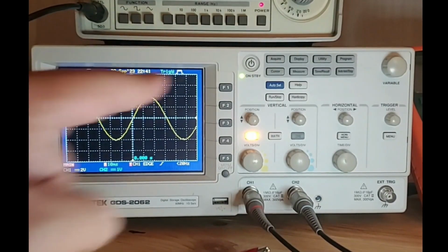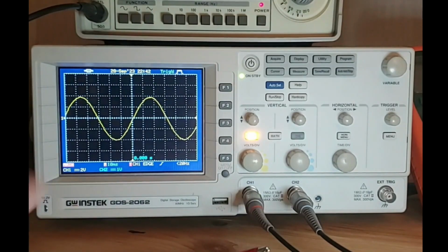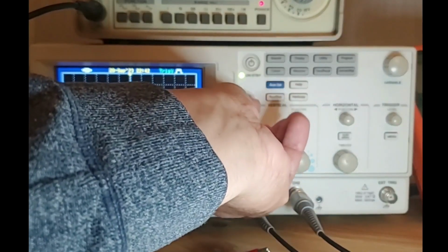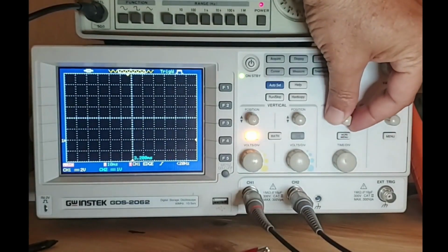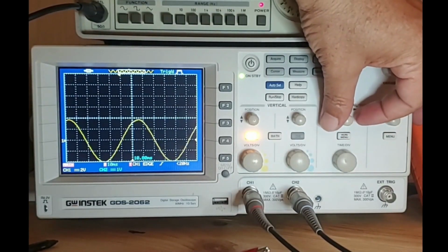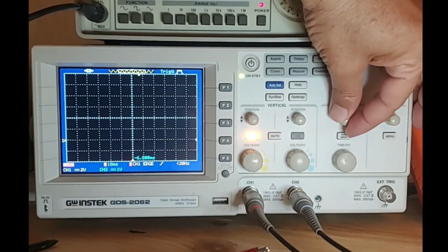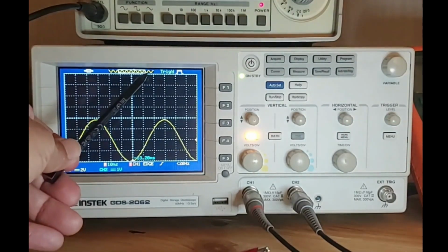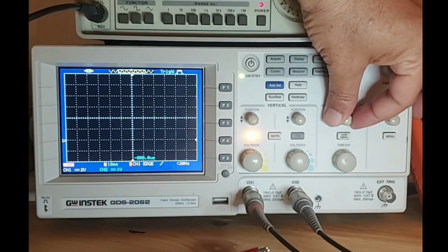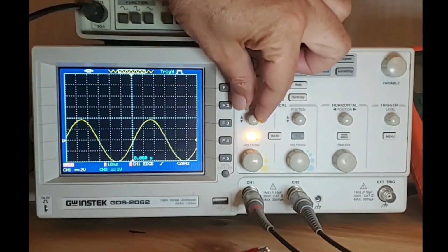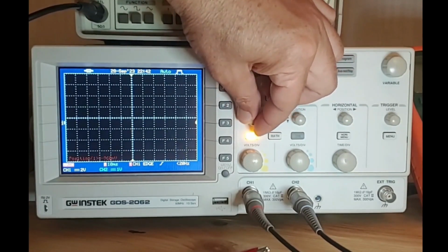Now let's see what the vertical position will do. I can move this waveform down, for example. Now this is my reference point, which represents 0 volts. So I have 2 divisions above and 2 divisions below. I can move the waveform up and down, and using the horizontal position, I can move the waveform left and right. The location is indicated by this arrow over here. Most of the time, we would like to keep it in the center. All right, and I will put the vertical position in the center as well.